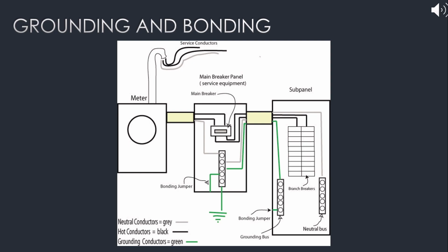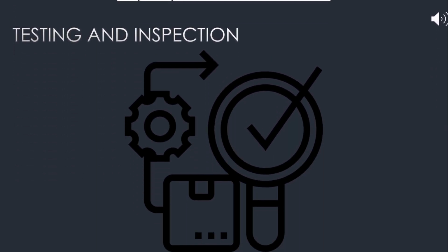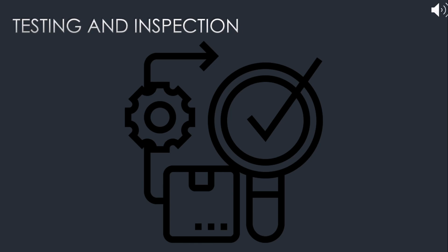The purpose of the equipment grounding or bonding conductor is to provide the low impedance fault current path to the electrical supply source to facilitate the operation of circuit overcurrent protection devices in order to remove dangerous ground fault voltage on conductive parts. Like consistent maintenance, testing and inspections also ensure that all equipment required for production is operating at 100% efficiency and that the product design and installation meets the requirements of professional judgment.